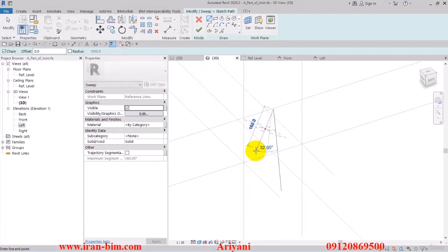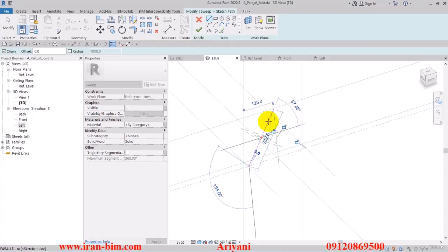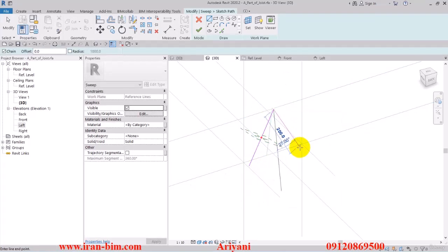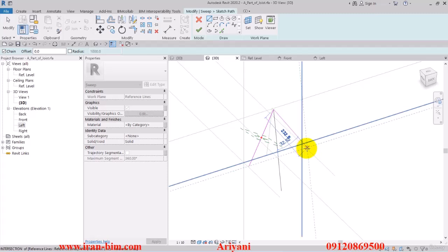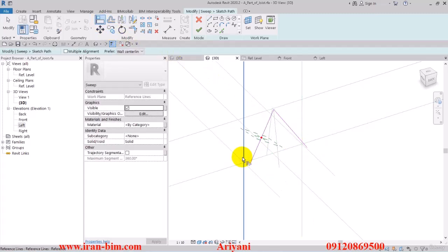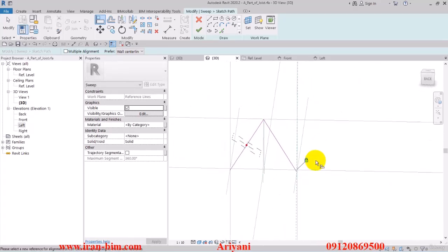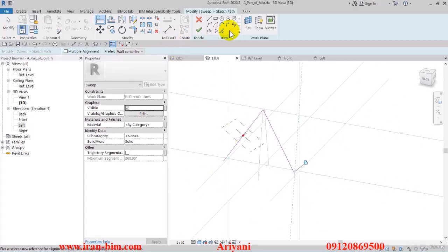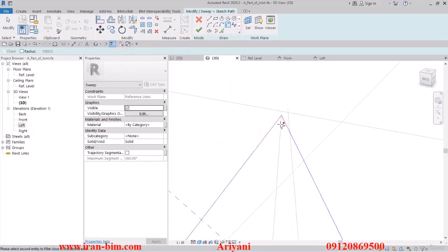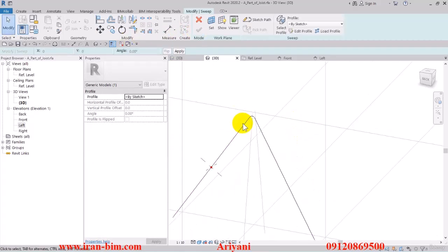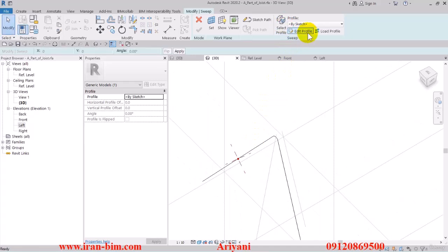So then I'll go here and draw from this point to this one. And then from a tip of this point, we draw down to here. Then I'll select a line, then click here, and then this one with this one. Cancel here, and then this one with this one, and then lock this one with this one. All right, okay. After doing that, I'll select the fillet, then click on this part. So for R, we'll put in 5, and then lock this part, and then finish it up.